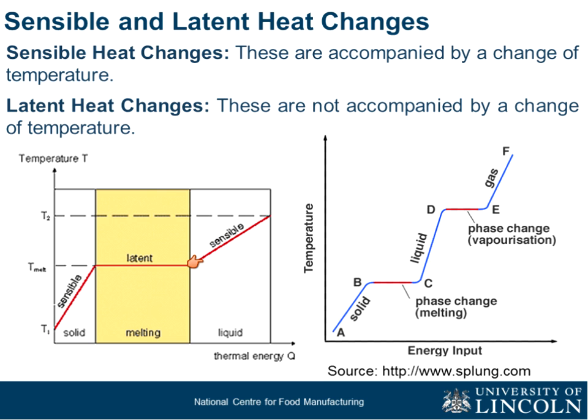So you should know the difference between the two, because when you are calculating your heat supply, you use a different formula for latent and for sensible heat changes. For sensible heat changes, the formula for your quantity of heat supply will have a change in temperature. But for latent heat, it will not. Otherwise, if there's a change in temperature of 0, that shows that energy is not supplied.